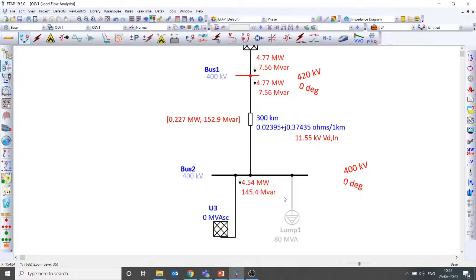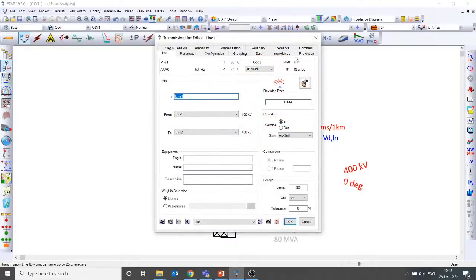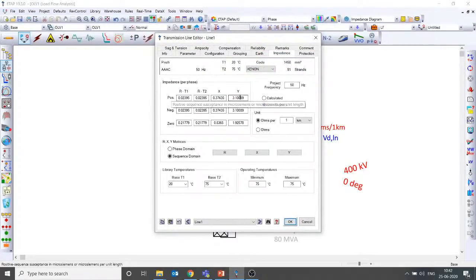And Sneha asks, why do you use positive sequence shunt capacitance 0? Can we not make any sequence value 0? Yeah, that's a beautiful observation, Sneha. I appreciate it. I have done some analysis and changed it to 0. So your question is why not negative sequence and zero sequence? Your point is very valid. Load flow analysis takes only the positive sequence into the picture because we are performing a balanced load flow. In a balanced load flow, only positive sequence matters. Negative sequence and zero sequence do not really matter. Whatever value you change, it will not affect the results.